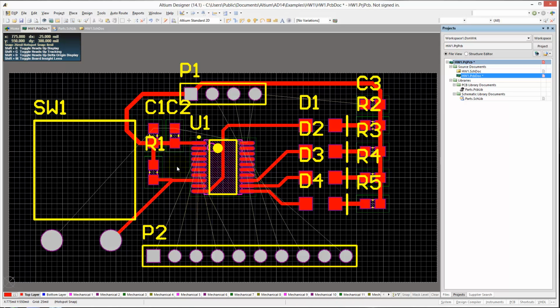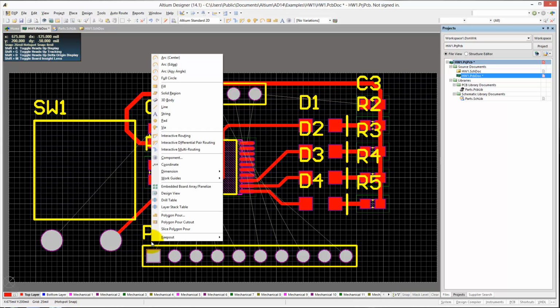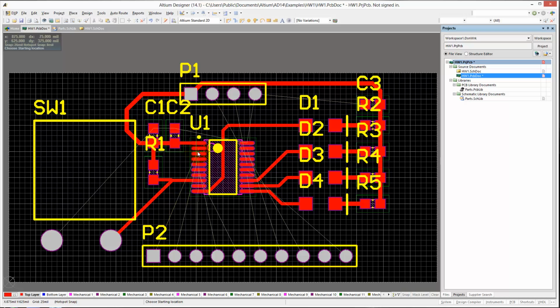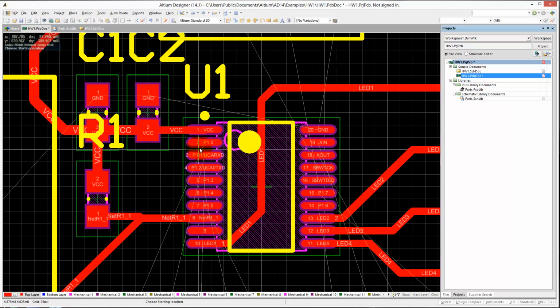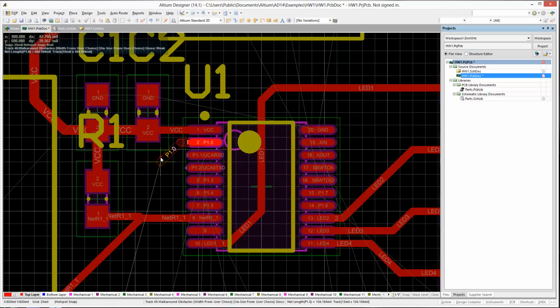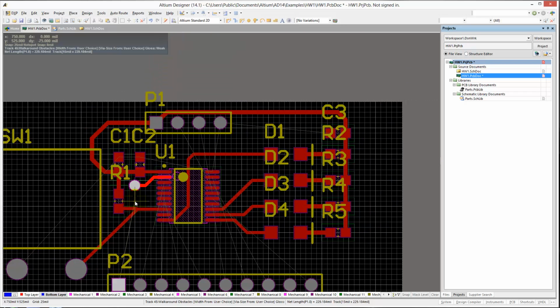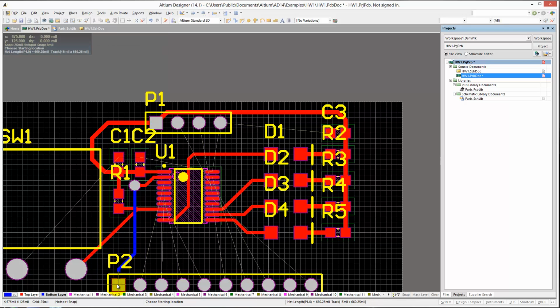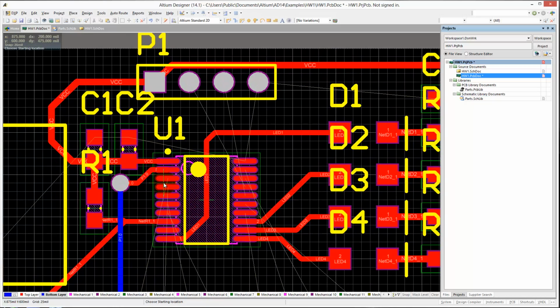So what we have to do is actually go to the lower layer, move over, and connect it to there. So what we do is PT, zoom in a little bit here. So we route this out, and then I hit the star key on your keyboard. You get a big hole, and now if you move on, you can see that the trace is now blue, which means that we are on the bottom layer. And since these are all pins that are connected at the top and the bottom, this will actually work. And we can do this for all these different pads here.